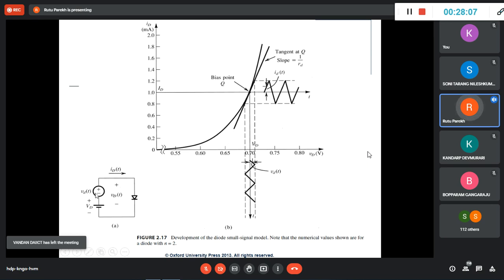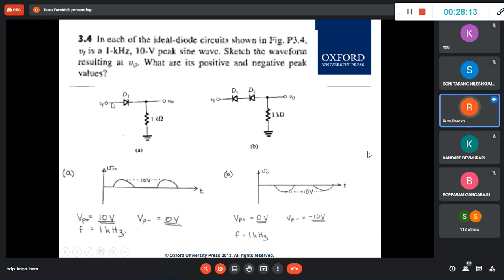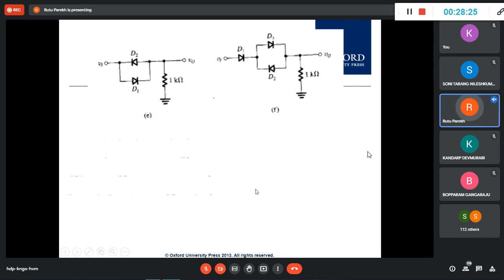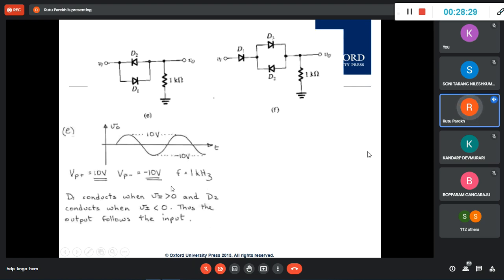And if it is already high volt, like as I showed you here, if it is 100 volt and just one diode, what will you get? In a practical, realistic case, it is 99.3 volt. So then you don't need biasing. You don't need this because here it is already high volt, it is operating, it is working.